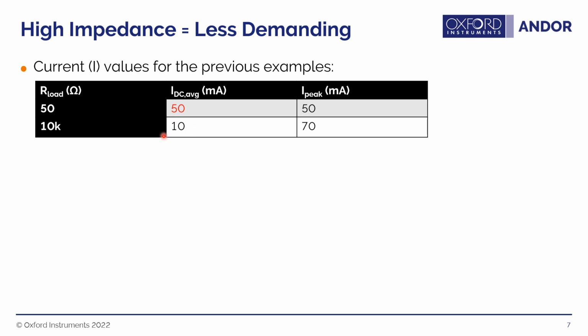Whereas overall, you're using less power on average for the mismatched high impedance system, but the peak signal goes high. So you want to watch out to make sure that the peak voltage and current don't exceed the rating of the equipment that you're using. And so overall, for the iStar, it is designed to be used, I have the numbers on the next slide, I think, slightly, you want to basically keep it above 0 up until 5 volts and then stay within that range of